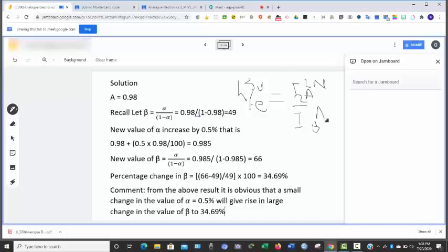So amp will cancel amp. So if it is 30, it means if this one is now 1, this one will be 1 times 30, which is 30. If this one is 40, it will be 40 times 30 for this amp. So any little change in this IB will give us a very large value for this collector current.